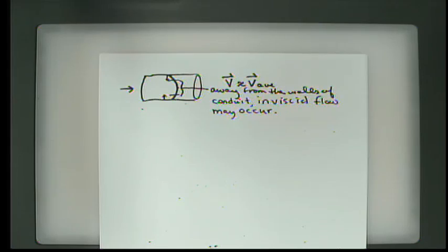Right. So how far away from the walls of the tube, and to what degree, and how much of the fluid we can omit, and what that nosing out profile looks like, those are all dependent upon the flow regime itself. But when we talk about viscosity and inviscid flow, those are sort of the ideas that we come up with.